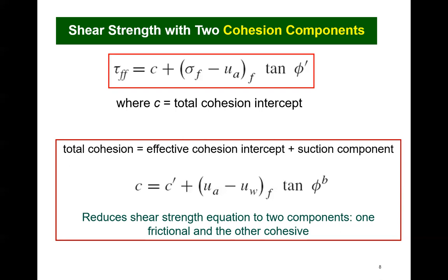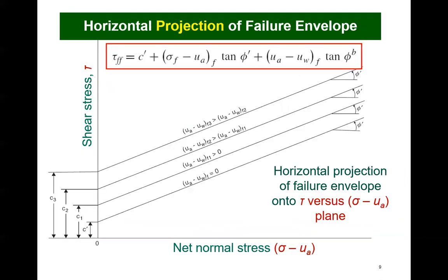Constants associated with plasticity solutions, such as the bearing capacity of a soil, are still applicable for calculating the effect of soil suction on the analytical outcome. To further clarify the nature of the shear strength envelope for an unsaturated soil, the effect of cohesion due to matrix suction can be reduced from a three-dimensional surface to contours on a two-dimensional plot.